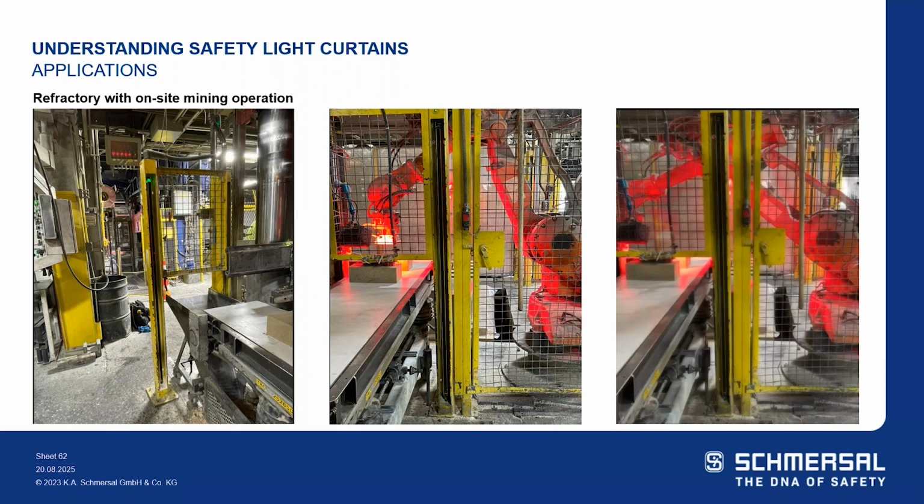They tried the most common fixes with shielded cable, trying to isolate all the control cables, separate conduit runs, trying to avoid parallel cable runs. They were swapping out transmitter and receiver mounting locations, but we gave them an SLC 440 COM to test out, and they temporarily installed that in place of one of the Allen Bradley and one of the Omron light curtains. After 2 weeks of testing, they didn't experience a single trip of the light curtains from Schmersal. So our primary selling point was the ability to perform in an environment with a great deal of electromagnetic interference.